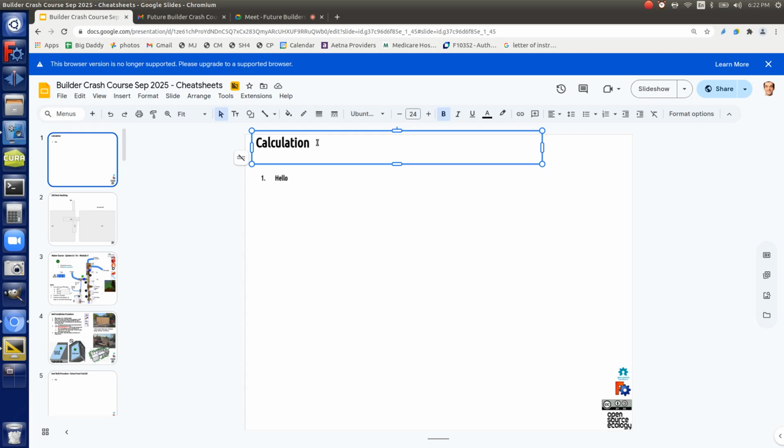It will crumple right under it because now you're getting into other things like bending. As soon as you get bending, that's a different kind of force. So you can't do it. That 100-foot rod will start sagging by itself, just by its own weight. So think about that. Yes, it's 140,000 pounds per square inch, but that doesn't apply to flexion. You only have so much flexional strength.